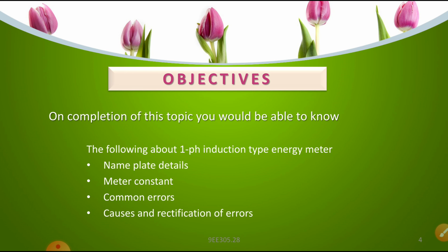If you want to use an iron box, before going to supply we check whether the voltage is 230 volts or 110 volts, whether it is 50 Hz or 60 Hz, and the class of insulation, whether it is A type or B type or C type. As electrical people, what is the rated full load current, the voltage, the power factor? All details may be present on the nameplate.